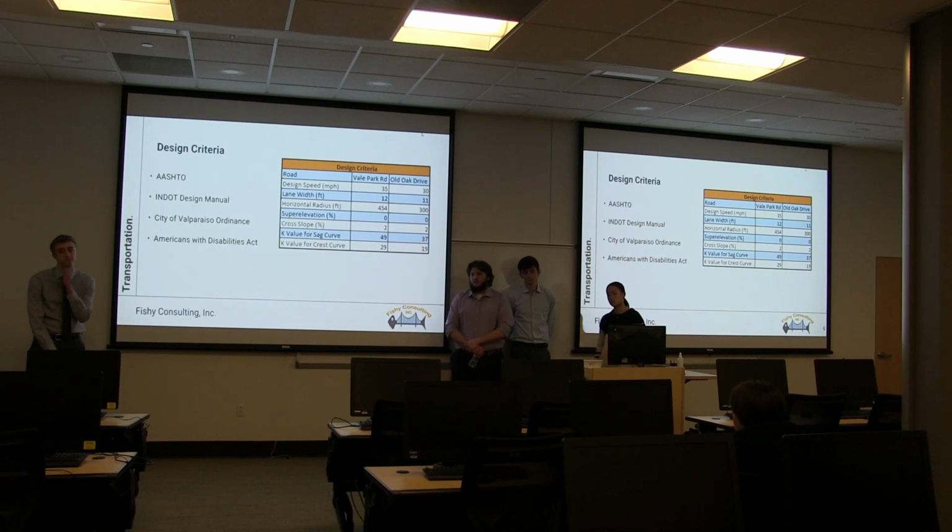Normally, on a roadway profile, you would show the ditch profile also, rather than it being a constant, this far off, this far down. If you run into a sag, you may have to adjust that grade. I wonder if you're talking to each other about how you're going to get the water all the way down to the creek, because I know that road goes up and then goes down, so you need to figure out what the grade of that ditch is. So you two need to talk to each other, mostly a comment.